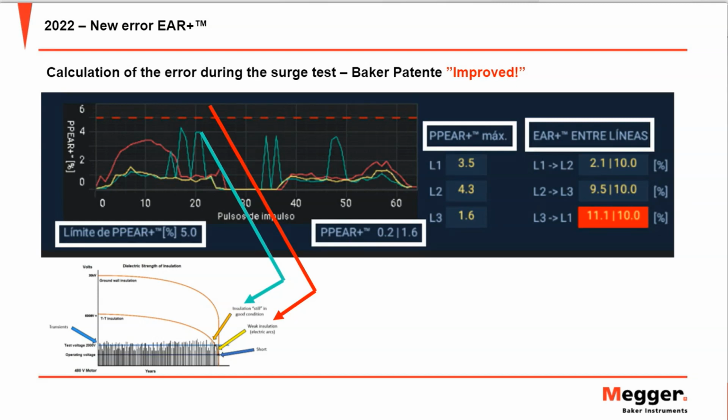the arc. So this new concept of diagnostic is going to tell you that the motor is in good condition and can work, but for example, if we are testing the motor in the industry every 6 months, we do not have to wait 6 months in order to do the next maintenance, because we have this information. So the insulation still is in good condition, but we are close to having the arcs. So then we can reduce the time. Maybe in 1, 2, or 3 months, we can do another inspection in order to identify if this information is